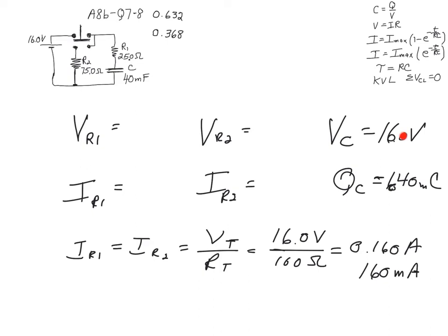So given the 16 volts, it means that we have to have 16 volts spread out over these 2 resistors. And because there are 2 resistors, they're not going to both have 16 volts, right? Kirchhoff's voltage law. And so how do you find how the voltage divides? You have to find the current. So we know how to do that. We have 16 volts, and that voltage is across 2 resistors, and the 2 resistors are in series, so that's 100 ohms of resistance.